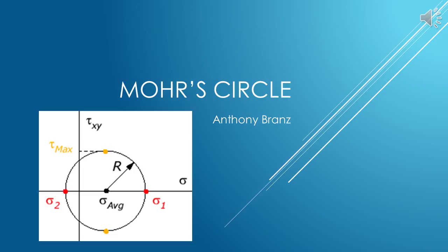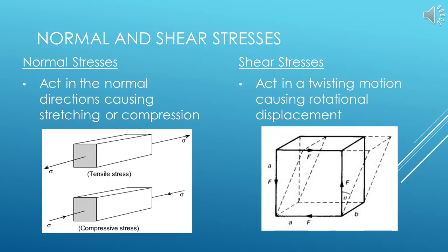It's a two-dimensional visual tool to analyze stresses and strains in a material. It's one of the most helpful tools I've learned in my curriculum, and it is surprisingly easy to use. Plus, in simple applications, it requires no math. The Mohr circle is used to find the maximums of several values.